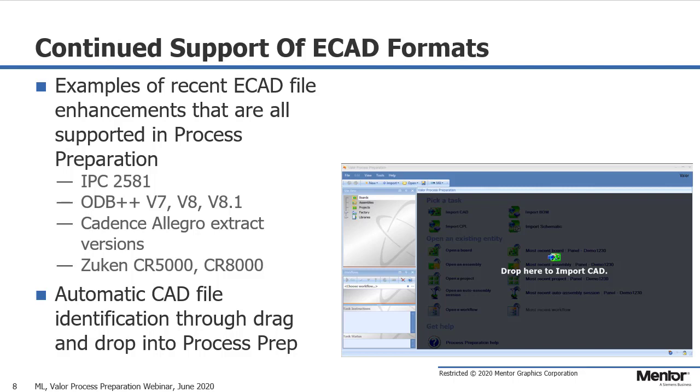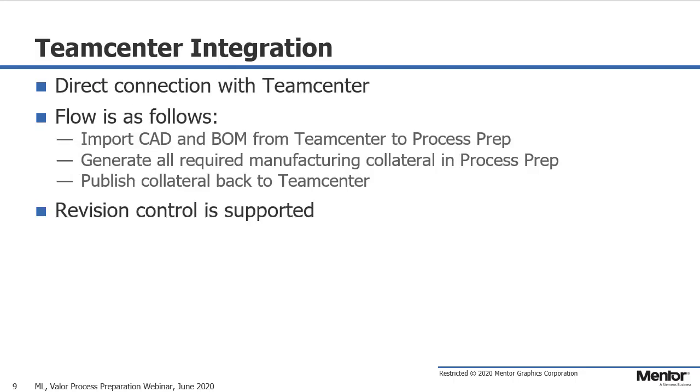Continued support of imported CAD and CAM formats is critical to seamlessly getting data into a process engineering application. We recently added IPC 2581 and then followed up with revision A and B of this format. ODB++ has been updated with versions 7, 8, and 8.1. Zuken has updated CR5000 to CR8000 Board Designer. New in 12.8 was the ability to drag and drop a CAD file onto the client and identify that file automatically. Since Mentor was acquired by Siemens, we have focused on integrating with a number of Siemens products, and one